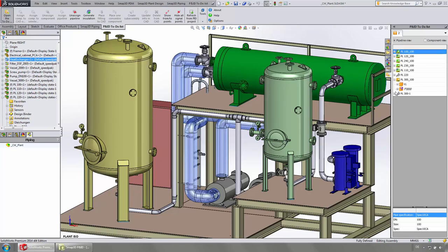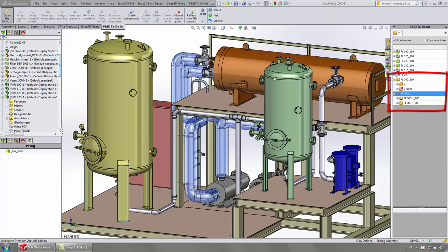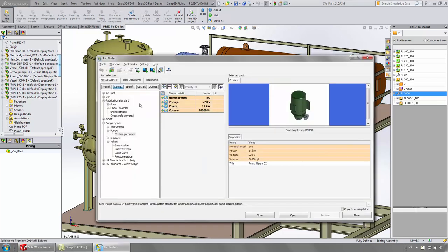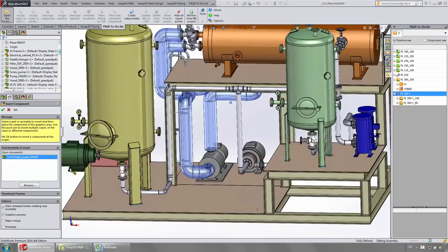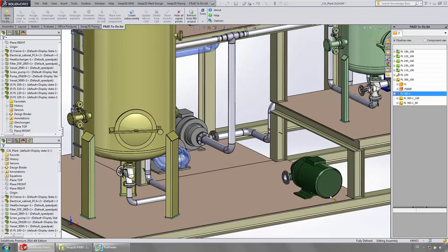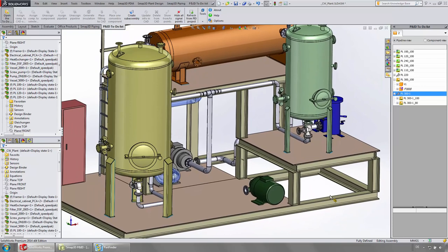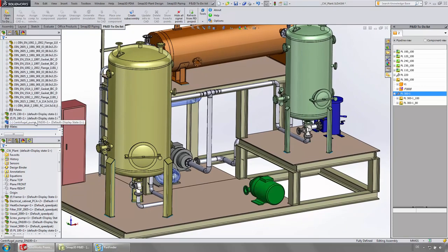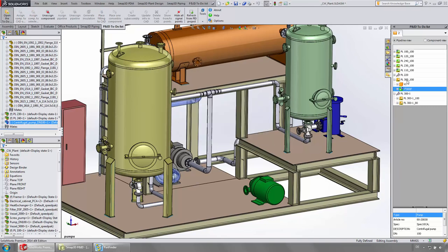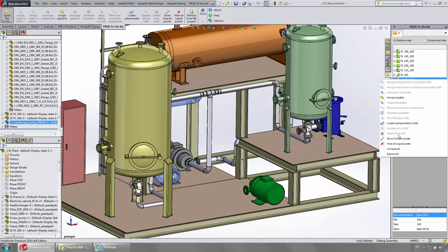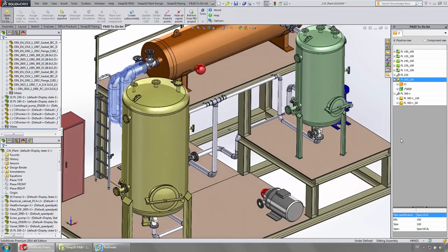The to-do list is helping the user implement changes according to the P&ID diagram. In this case, the pump gets placed first from the 3D library. And then we assign the component properties of P&ID to the 3D model. With the information from the P&ID, the 3D pipes are ready to be created. The function FromToPoints helps the user find the correct connection points.